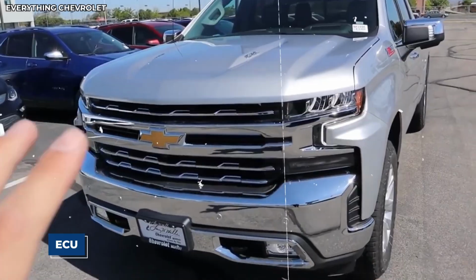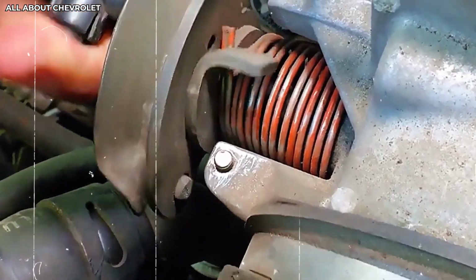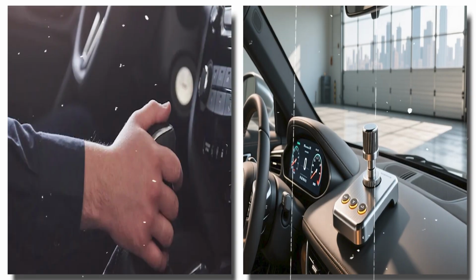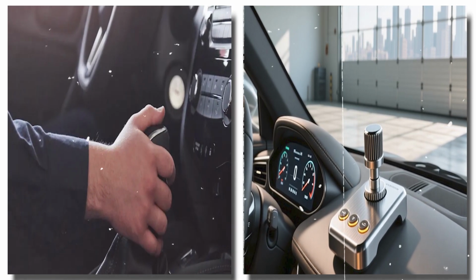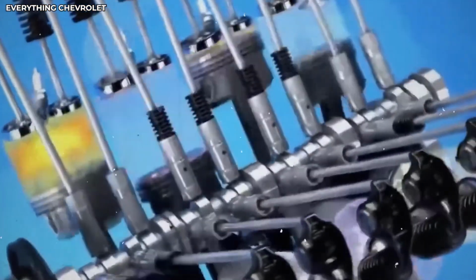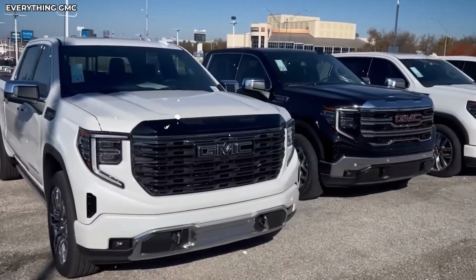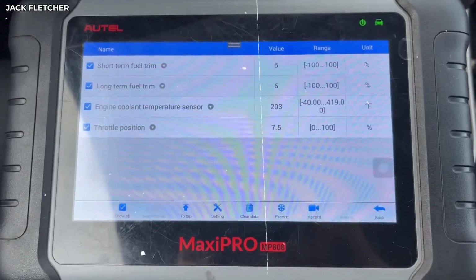That ECU receives your pedal position input, processes it through multiple algorithms, and then sends a command to a small electric motor on the throttle body, telling it how far to open. This happens in milliseconds, so fast you'd never notice the delay under normal circumstances. But here's where the problem starts. Ford programmed these computers with adaptive learning capabilities.